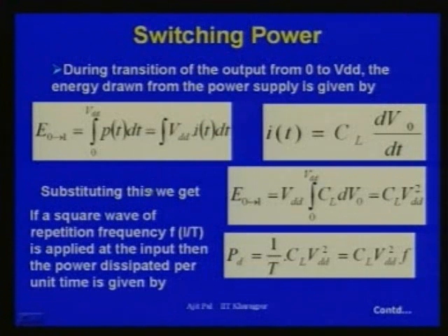And this is essentially the derivation of that equation. I am skipping it, not going into the details. You can derive it, that the power dissipation will be equal to CL VDD square F, and of course here we have not taken into consideration the switching activity. Here it has been assumed that the transition occurs in each clock. Whenever you take into consideration the switching activity, you have to multiply alpha L with it.